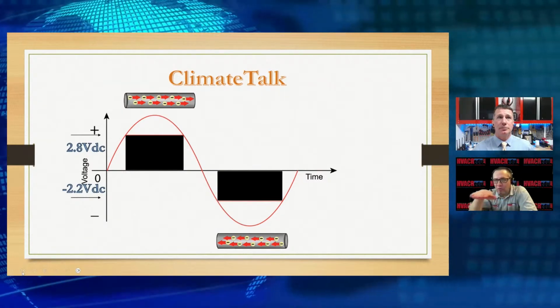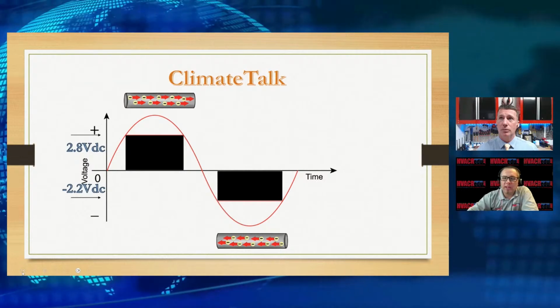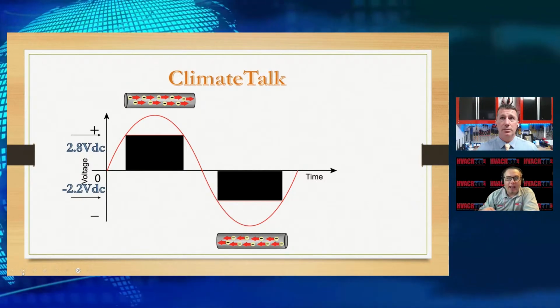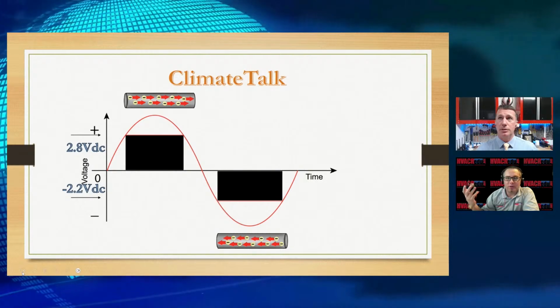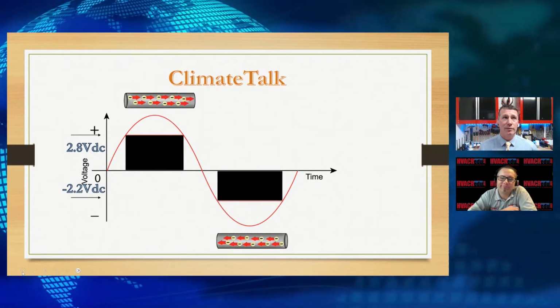And all we're actually doing is that zero voltage baseline. I don't know if y'all remember, maybe in some of the furnaces you plug in, if you have a 2-prong and you don't have that ground, and then all of a sudden your PC board doesn't like it. This is because it has no reference to ground. No reference point for our voltage.